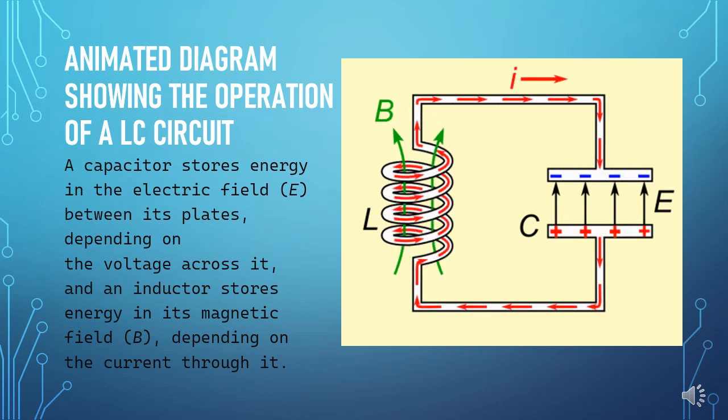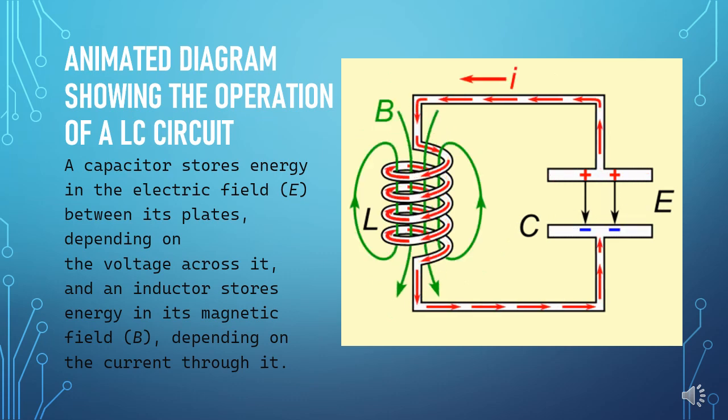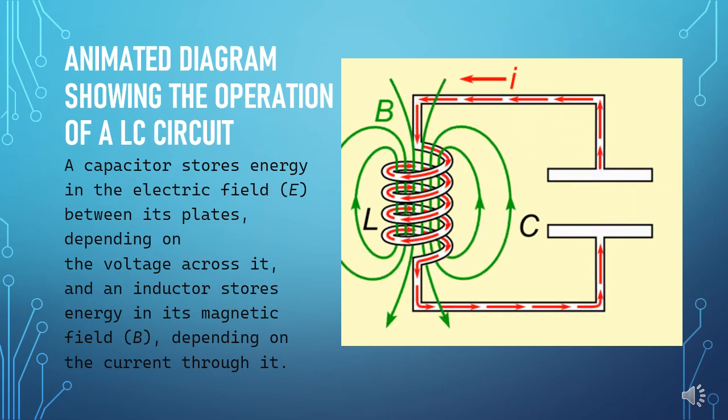The voltage across the capacitor falls to zero as the charge is used up by the current flow. At this point, the energy stored in the coil's magnetic field induces a voltage across the coil. Because the inductor opposes the change in the current, this induced voltage causes a current to begin to recharge the capacitor with the voltage of the opposite polarity to its original charge.